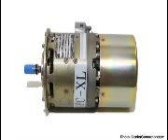After the loop rotates slightly past the 180 point, the black brush is contacting only the white segment and the white brush is contacting only the black segment. Because of this switching of commutator elements, the black brush is always in contact with the coil side moving downward, and the white brush is always in contact with the coil side moving upward.